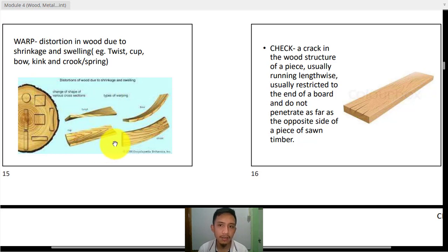Or maybe every other month or every other week they are trying to rearrange or flip the piling of your lumbers, so again, for the cross section of this lumber not to have distortion or undergo warping. And then we have also here what we call the check. That is a cracking on the grain parallel, or on the cross section parallel to the grains.